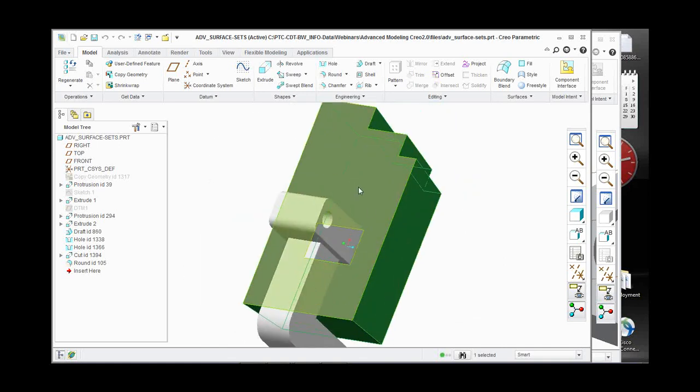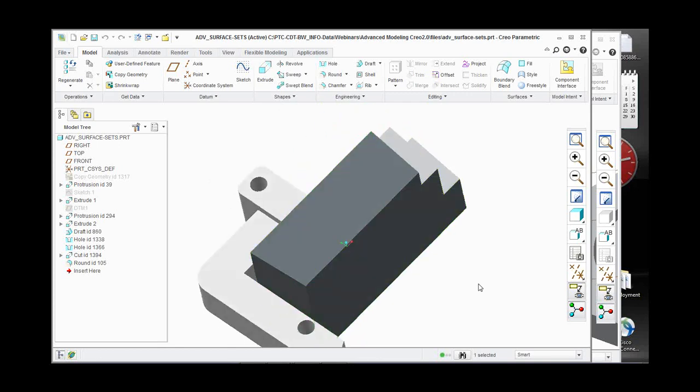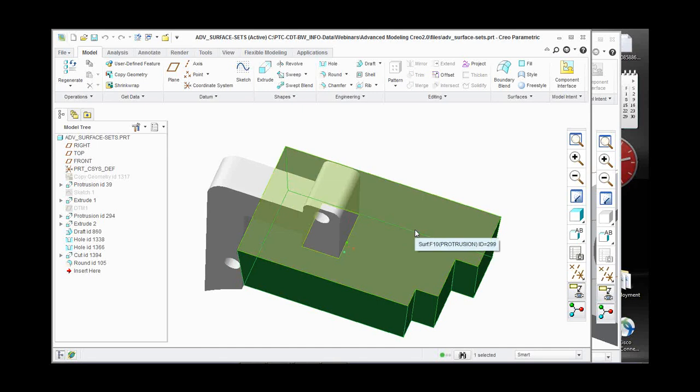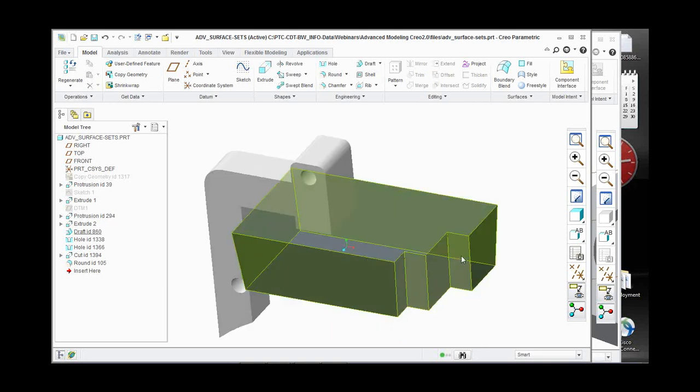of this top surface. So loop of this top surface, again, if I did it on the bottom, if I pick this surface, hold the shift button, come out to the edge, if I left click, I have selected all of those surfaces and I can offset them or do whatever you might do at that point in time, okay? That is called a loop surface selection. It's the surface, shift, go out to the edge, they highlight, you let go, and you can get those loops of that individual surface. This is called loop surface selection technique.